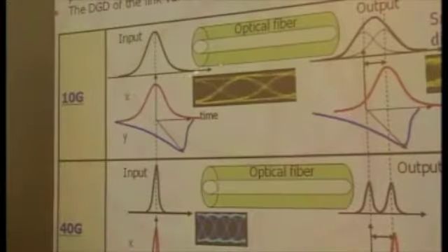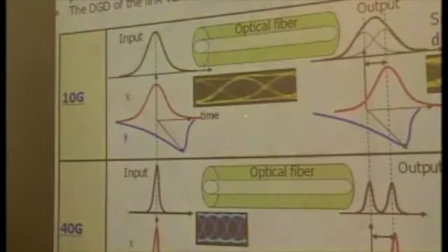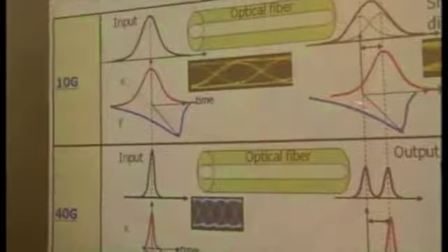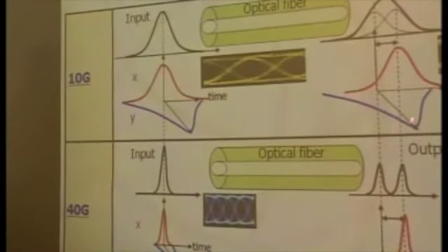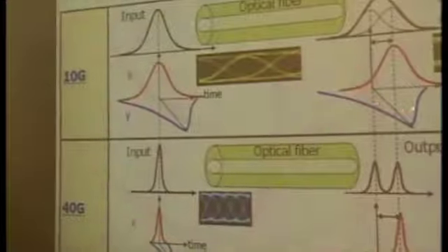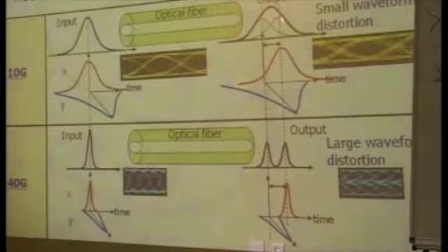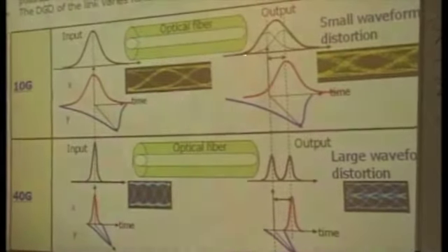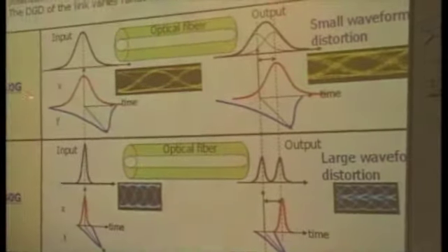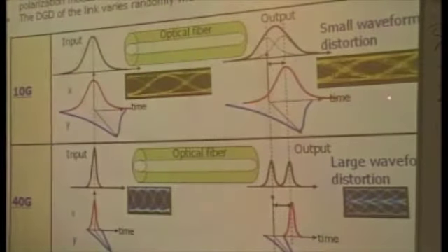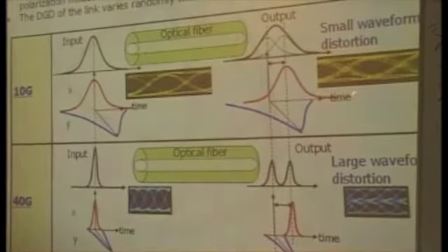Even if the transmitted signal is not degraded, at the output of the fiber PMD means a delay between these two signals split into two polarization states, and the synthesized power will have a broadened shape. So for 10G systems, you can see such a waveform distortion.